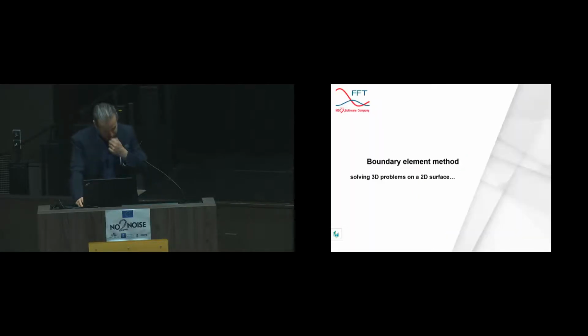Okay, exterior acoustics. As I said, I mainly focused on finite elements, explaining how to model a finite model by dividing it into a set of finite elements. But when you have exterior acoustics, you cannot do that, because as elements have a fixed size with respect to wavelength, you will end up with an infinite number of elements if you want to pave an infinite medium, and this will not work.